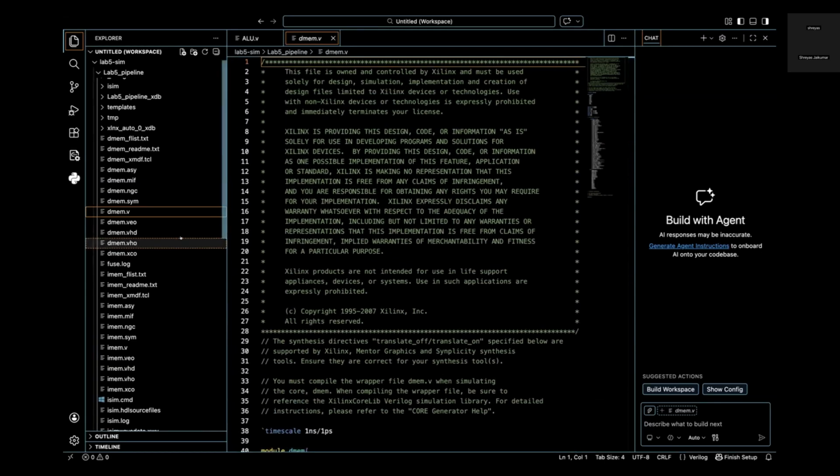This is just generated for us, and I'm just quickly going through that. We gave the exact specifications as provided in the PDF manual, that is choosing 64-bit wide data, 8 address bits, so 256 entries, whether we need write enable or not, write first or read first. Basically, in DMEM, you're not using port B at all, so it's just zeros, or in other words, don't care.